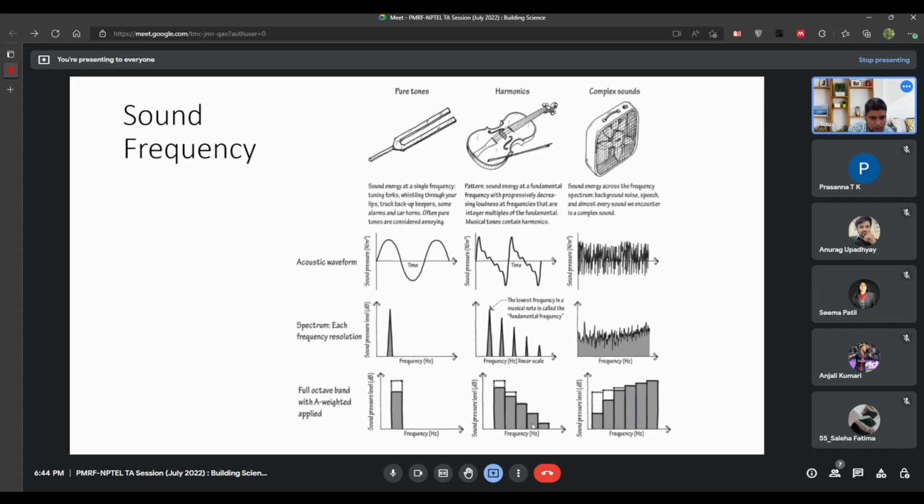And the last chart you look at, you would have been explained about dBA, where A stands for how the human perceives the sound at different frequency ranges. For example, if you have a very low frequency, for the same decibel output, what a human perceives will actually be less, which is indicated with this dotted line. The dotted line defines the actual decibel level, but the solid line is the human perceived, or A weighted, sound pressure level.